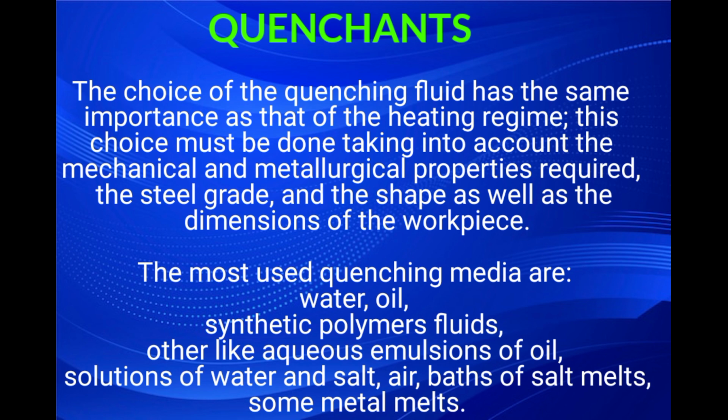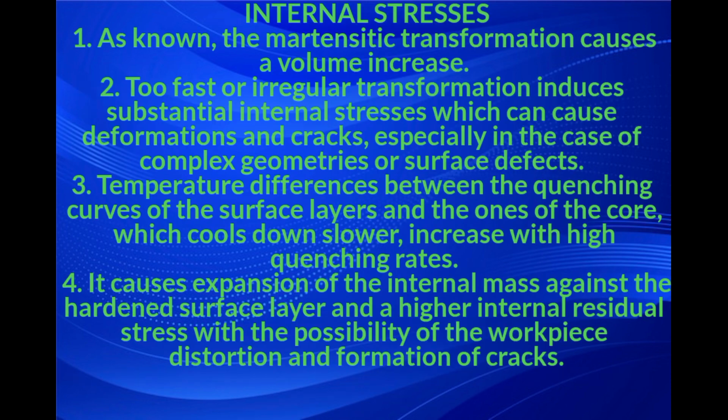The most used quenching media are water, oil, synthetic polymer fluid, others like aqueous emulsion of oil, solution of water and salt, air, bath of salt melt, and some metal melts.